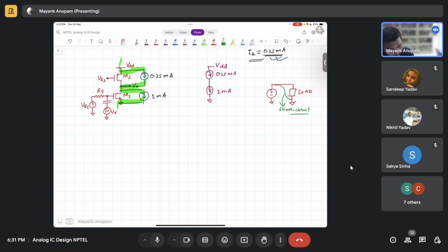So what happens in this condition? Why is this a problem? If you are touching it, what is going to happen to you? Actually, the impedance might be zero, which is why the current will be infinite. Yeah, current will be extremely large, right? Not infinite in practical appliances, because there will be some impedance for this device also, right? So not infinite, but very large. A large current will suddenly flow, which can completely destroy your device, right? Something will burn somewhere. It's not good.